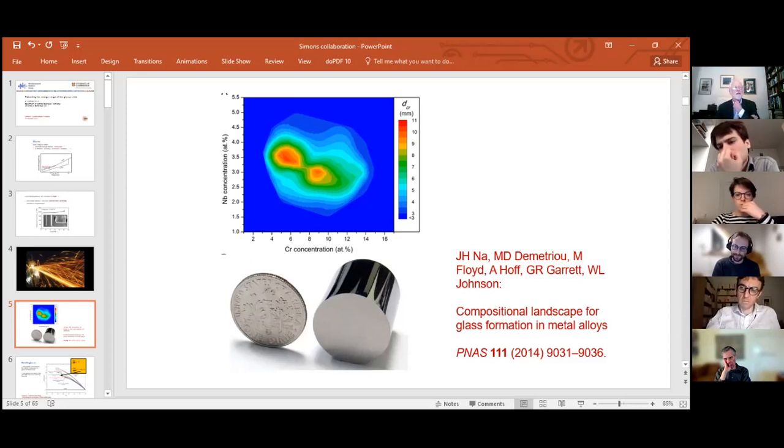So for me, it's something like an analogy of dislocations in the crystal, that they will dramatically affect the plastic properties, but not with similar dramatic effect change the elastic properties. So we're putting in some sort of local features that have effect on some properties and not on others. That effect on the elastic properties, however, may well not be the same for the extreme rejuvenation.